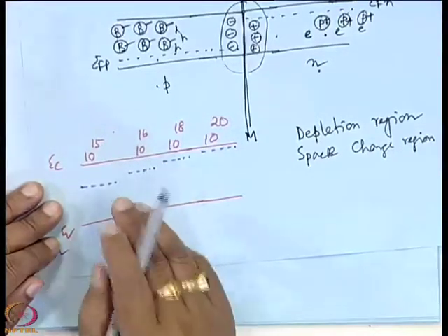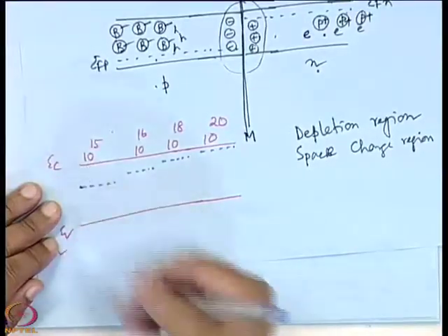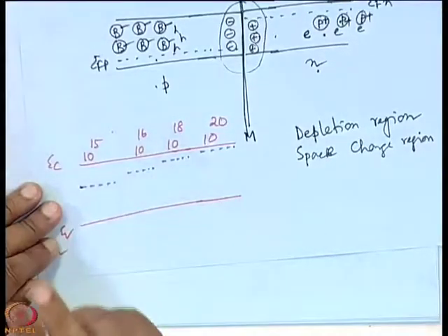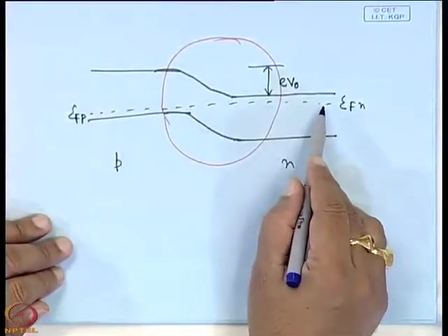That means the Fermi level changes as the carrier concentration changes. Since near the depletion region or inside the depletion region the charge carriers are fewer, this will be more. That means the difference of the Fermi level from the conduction band will be more. So, that is the reason that, to align the Fermi level, the band will bend itself.